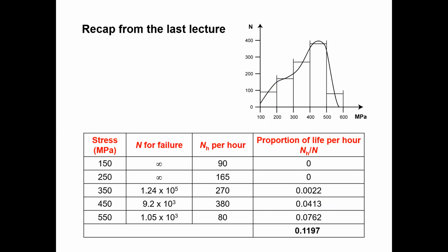If we apply different magnitudes of stress cycles, we need to consider this kind of statistical data, meaning you need to calculate the damage to the specimen from that particular stress cycle. But keep it in mind: if the stress cycle magnitude is less than the endurance limit, you don't need to consider that stress. It will not affect the lifetime of the specimen.